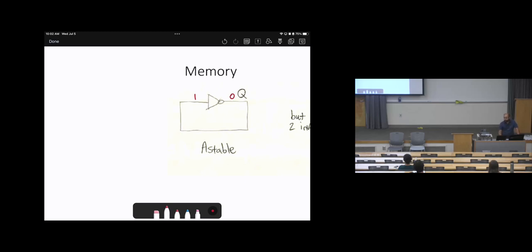It will be stored as 0. Then 0 will go here as feedback, and it will be 1. So what's happening here? The data will not be stored because it is sometimes 0, sometimes 1. It will change a lot. This creates something called astable, or unstable: sometimes 0, sometimes 1, sometimes 0, sometimes 1. This is not acceptable, it cannot store data, and does not meet our target.